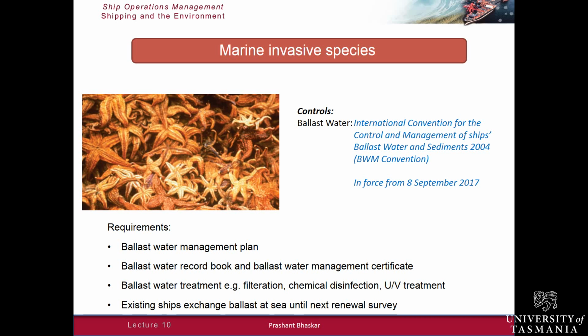New ships should have a ballast water treatment plant, or they should treat the ballast water either through filtration, chemical disinfection, ultraviolet treatment, or any other treatment. Could be heat treatment, whatever is cost effective for the ship. Existing ships are exempt from installing the ballast water treatment plant until the time they have the next renewal survey. But until such time, they should exchange ballast water at sea.